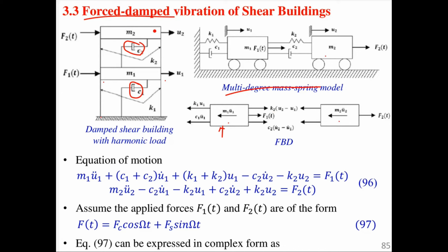Because there is a motion on the second floor, you see now there is a force: the stiffness due to the column on the second floor will also act on the first free body diagram. So these internal forces, without drawing them, you might not be able to see the interaction between the different stories, different floors. Okay. Once you do it like that, you are able to sum these forces for one free body diagram.